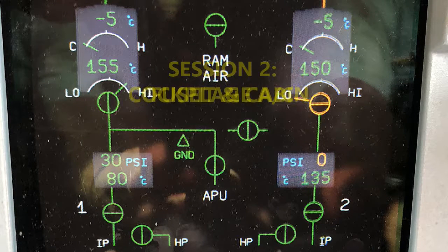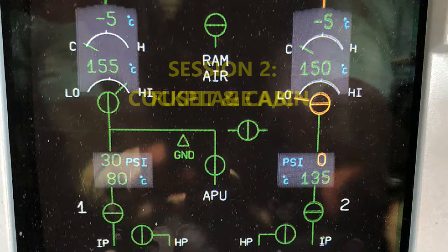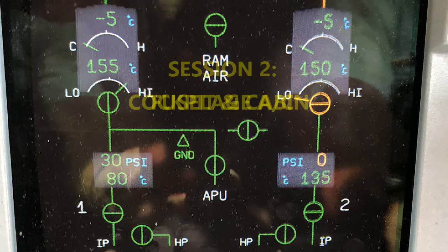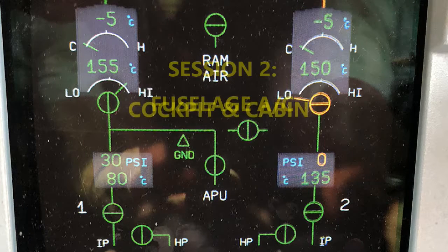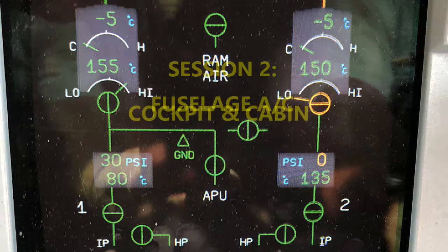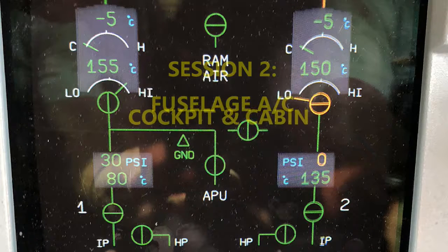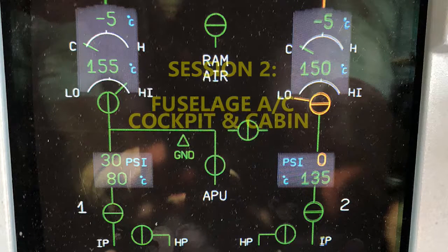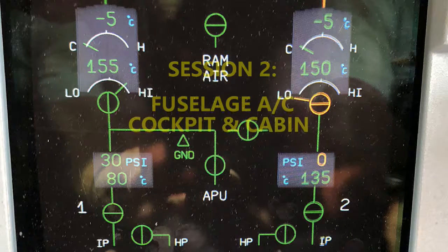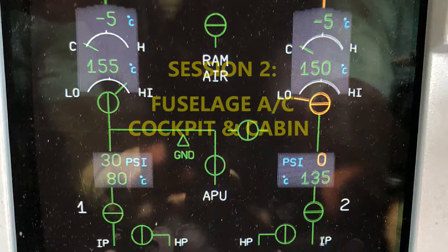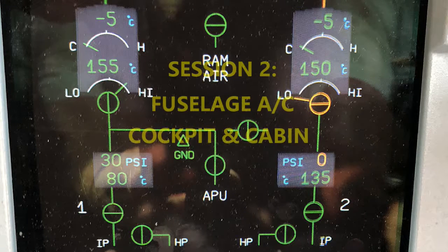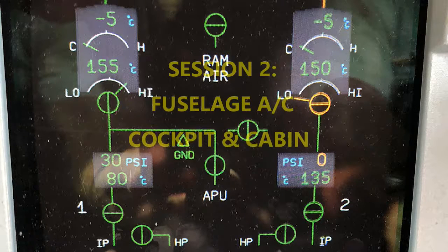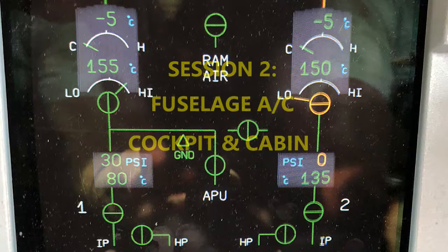They have alarm functions. Okay, those are your ECAM warnings. There's a self-monitoring. Remember, a lot of these computers, most of them, if I can say all of them, probably have this self-monitoring and being able to do the BITE tests. Also looking for any kind of indication of faults. They also have cabin pressure sensors, the Airbus interface to the SDAC, okay, on the ECAM. Discrete interface to the landing gear CIU, also with interface with the other CPC, the cabin pressure controller, and then interface with the outflow valve actuator.